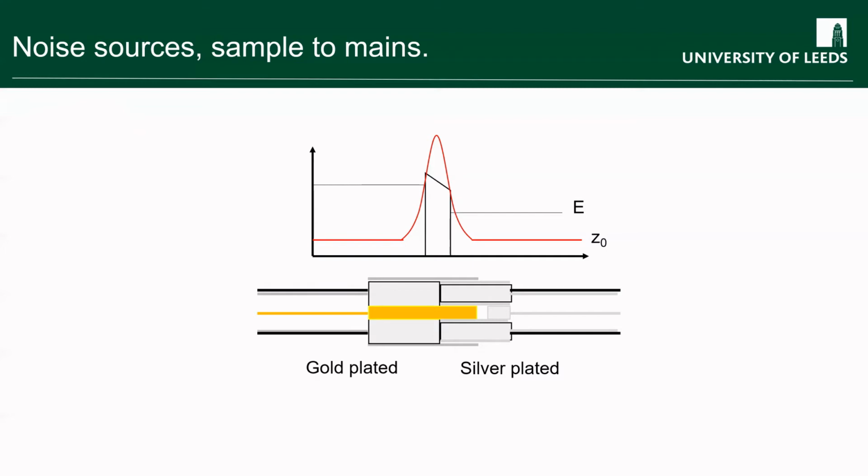And then as you go across the connector, you also want to think, it's not just the signal line that has to connect through, but also are you connecting the ground or the shielding through? Because if you introduce a bad connection on some ground line, then you're not going to have a well-defined ground on your experiment, because it's now got a big resistance. And the point about a ground is it should be the lowest resistance path you can get that discharges any electric fields or electric charge that builds up back down to the earth. So again, high quality cabling and high quality connectors can make a substantial improvement on your measurements.